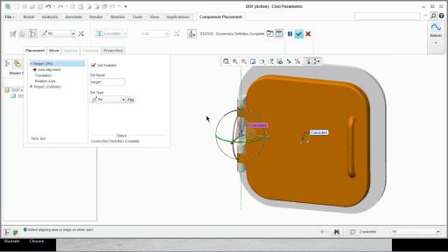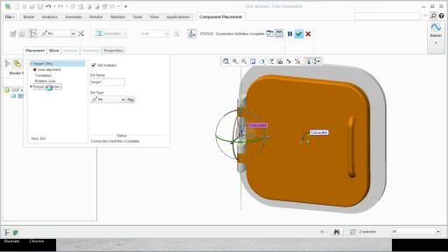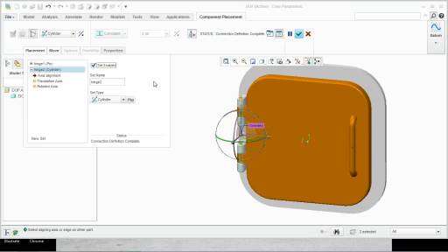Again, there are 6 degrees of freedom, 3 translations, 3 rotations. So by adding this hinge cylinder, I am unnecessarily restricting the same degree of freedom and enabling the same degree of freedom. Okay, so as of now I'm going to disable this. So just imagine that I only have a pin connection. Now I get into mechanism.